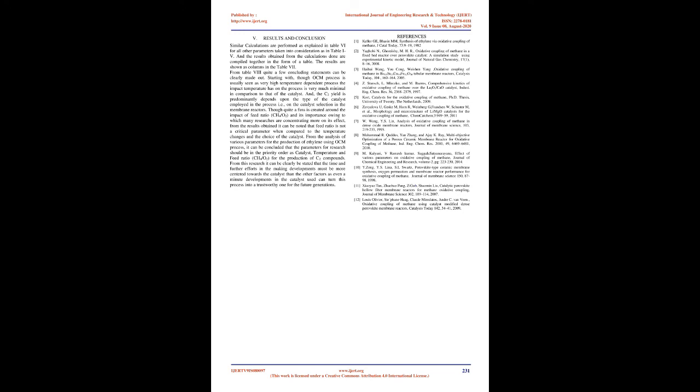Starting with, though the OCM process is usually seen as a very high temperature dependent process, the impact temperature has on the process is very minimal in comparison to that of the catalyst. And the C2 yield predominantly depends upon the type of catalyst employed in the process, i.e., on the catalyst selection in the membrane reactors. Though quite a fuss is created around the impact of feed ratio, CH4/O2, and its importance, owing to which many researchers are concentrating more on its effect, from the results obtained it can be noted that feed ratio is not a critical parameter when compared to the temperature changes and the choice of the catalyst.